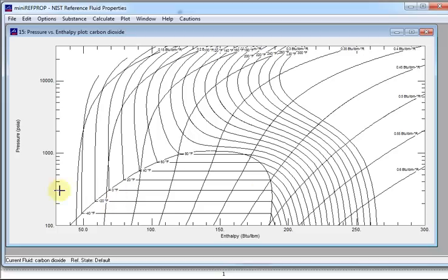It looks like the saturation pressure is around 300, just eyeballing it. Why did we plot lines of constant S? Because in our traditional vapor compression refrigeration, what comes out of the evaporator is saturated vapor, somewhere along here. Saturated vapor, right? And if you had a great compressor, it would be isentropic. It would follow a line of constant S going up. That's why we put a nice line of constant entropy on this pH diagram. So maybe we want to think, okay, it's going to come out 0 degrees F, and let's say it comes out saturated vapor. I put it through the compressor. It goes along a line of constant S scooting up this way.